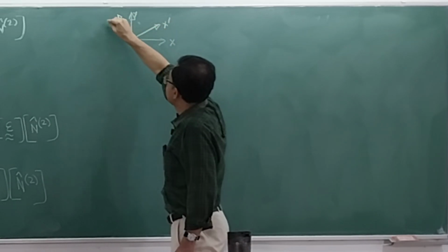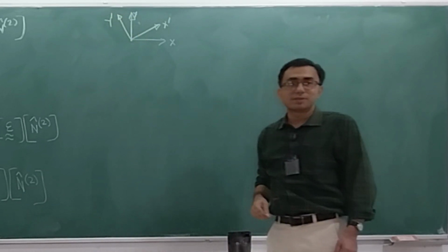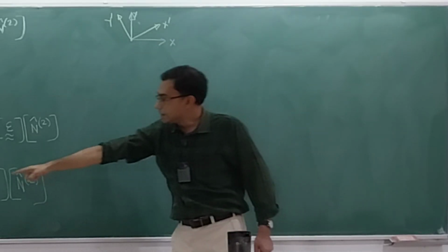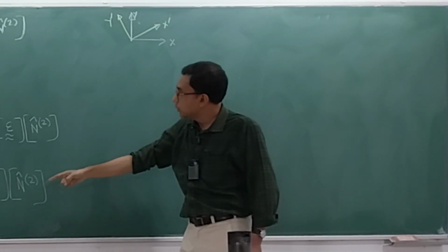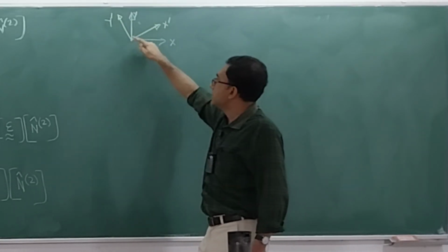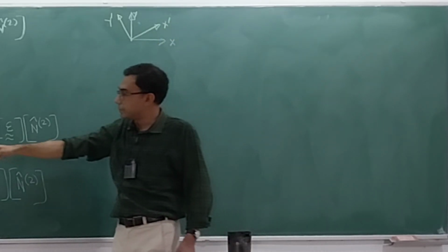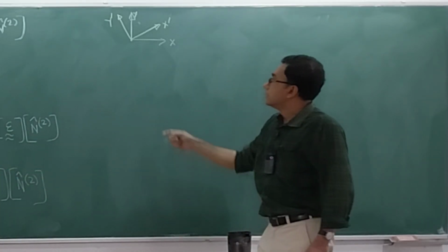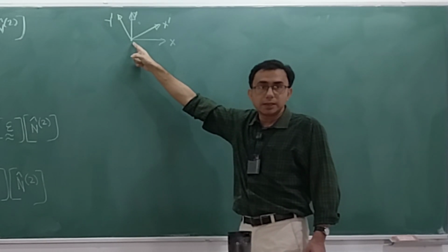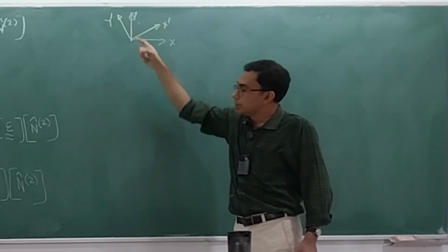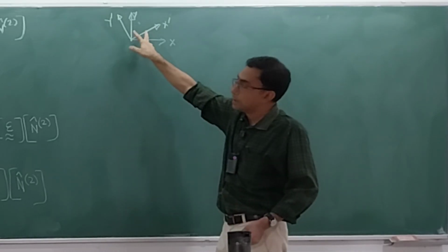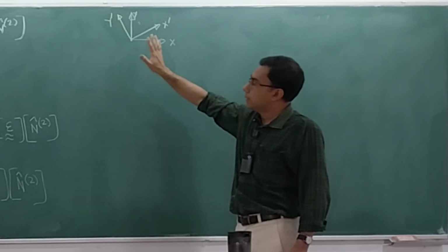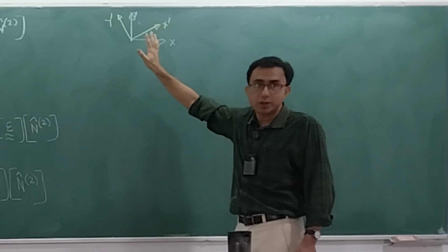And these may be x dash and y dash. You see where I am going with this? The n1 hat will be along the x dash and the n2 hat will be along the y dash. Initially the angle between them is 90 degrees, as it was supposed to be, because n1 dot n2 needs to be 0. And you have all the information with the epsilon. So given n1 and n2, you can find out the shear strain which will be present between these two line segments, between these two directions. Now, if you appreciate this, you have appreciated a lot actually.